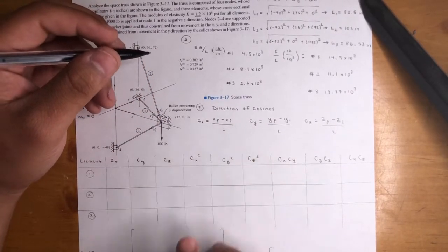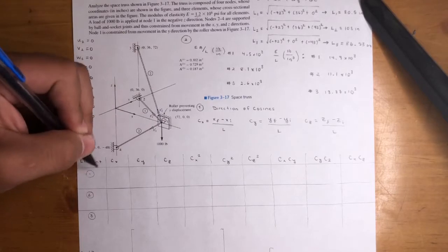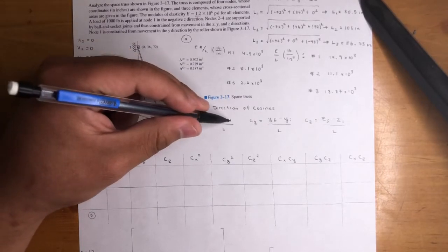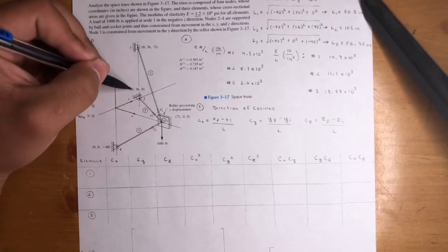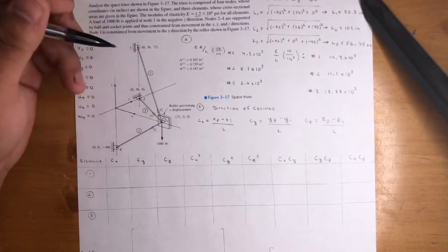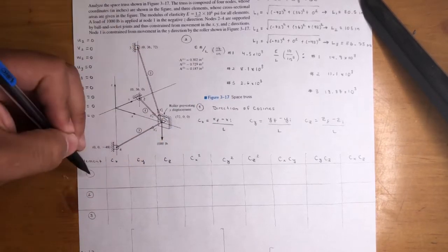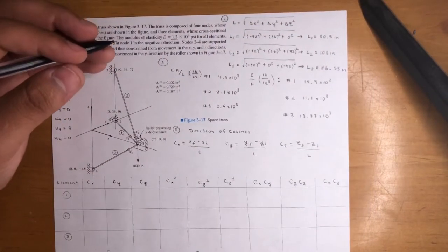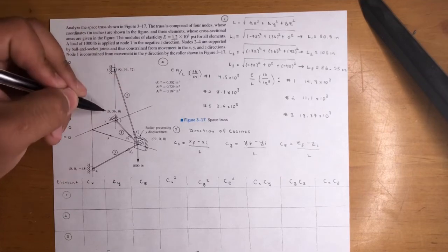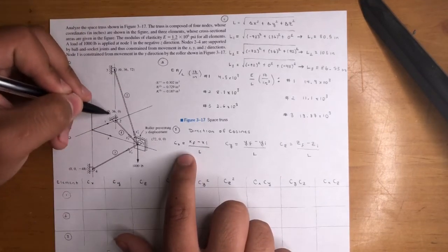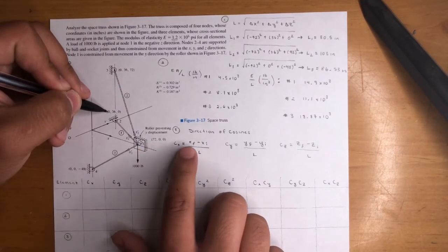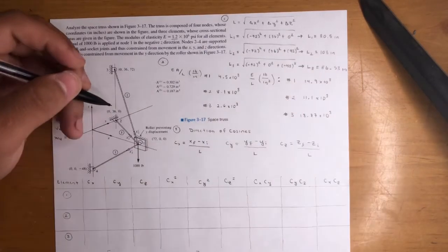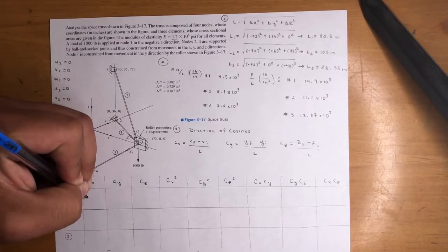Final minus initial. Okay, so we're gonna do it for each element. Let's just stick with 1 for now. It's the final minus initial of the x coordinate, divided by the length of the beam. In this case, it's 80.5. So for the first element we get 0 and 72, so it's 0 minus 72 divided by 80.5. If you do that math, you will get negative